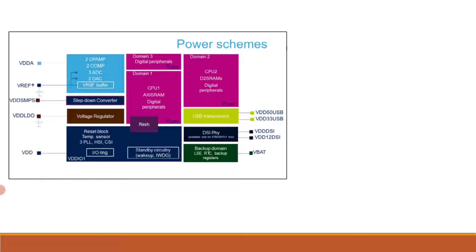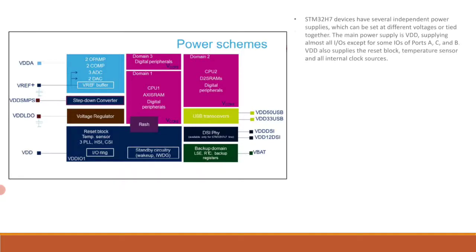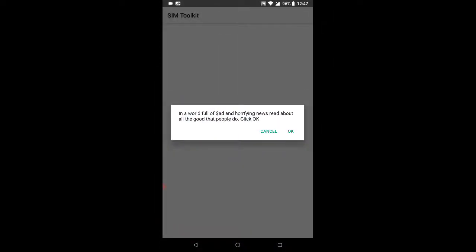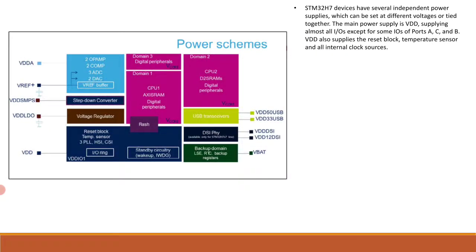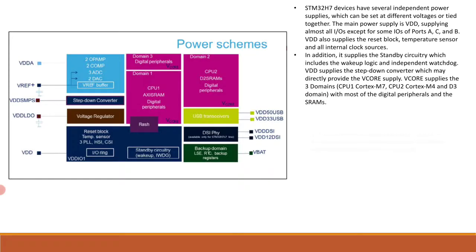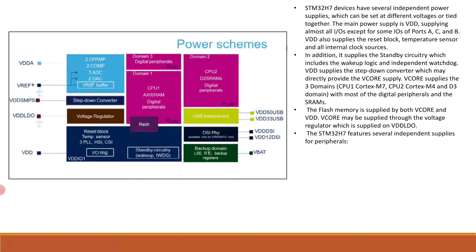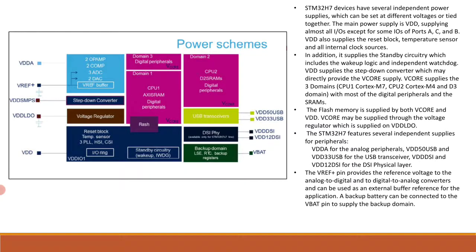The main power supply VDD ensures full featured operation in all power modes from 1.71 to 3.6 volts. For the analog power, device functionality is guaranteed down to 1.62 volts. This is the minimum voltage after which a brownout reset BOR is generated.